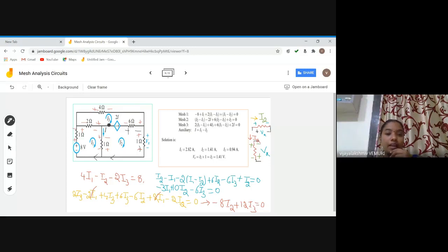So two currents are entering the node. What are the two currents? I plus I2, and one current is leaving. I plus I2 is equated to I1. Right? So I will be automatically equal to I1 minus I2. That is how you need to check how to write down depending upon the direction of the currents.